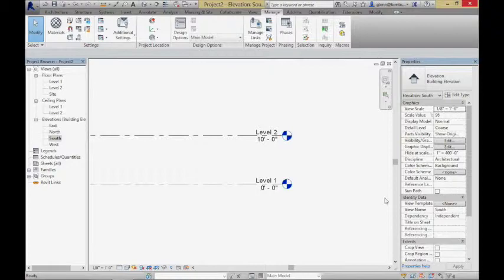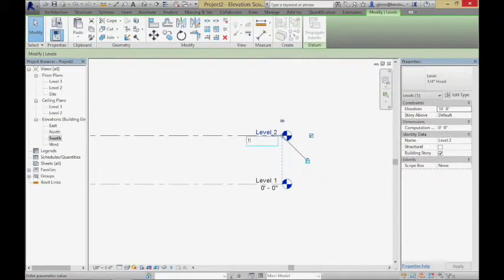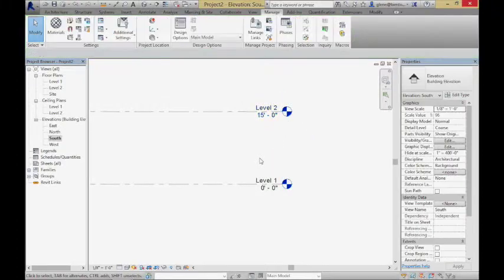If you've ever done real building projects, it's 12, 14, 15, because we need not only the space that we perceive between here and the ceiling, but also space above that for the structure, the mechanical equipment, the piping, all that stuff. So I'm going to suggest maybe 15 feet, not 10 feet. 10 feet is pretty low. Maybe in a residential scale that'd be appropriate, but I'm going to shift that to be more like 15 feet.